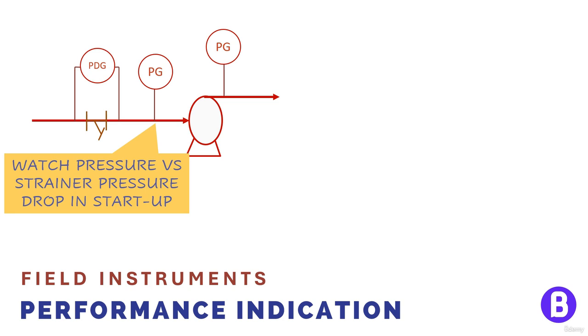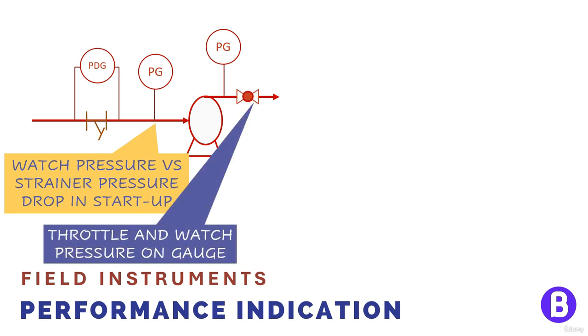On the pump discharge, it's common to throttle a valve on the pump discharge and watch the pressure gauge during startup. The discharge pressure can now be read on the pressure gauge, and once there is a continuous flow and back pressure is adjusted in the pump through the downstream equipment or components, then the isolation valves can now be fully opened and the system has started up.